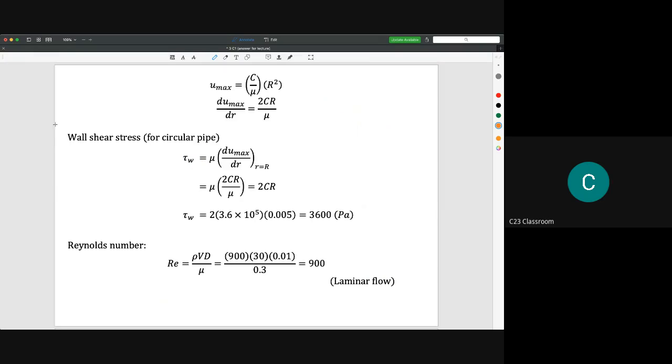In a circular pipe, we change the equation a little bit to this one. So we have tau equals mu du/dr, because we have a circular pipe here. The maximum velocity is at the center point, and the shear stress is reduced as the value of r becomes larger and larger. In Cartesian coordinates, it is equal to du/dy. Okay, and then we have this one, and in Cartesian coordinates again,